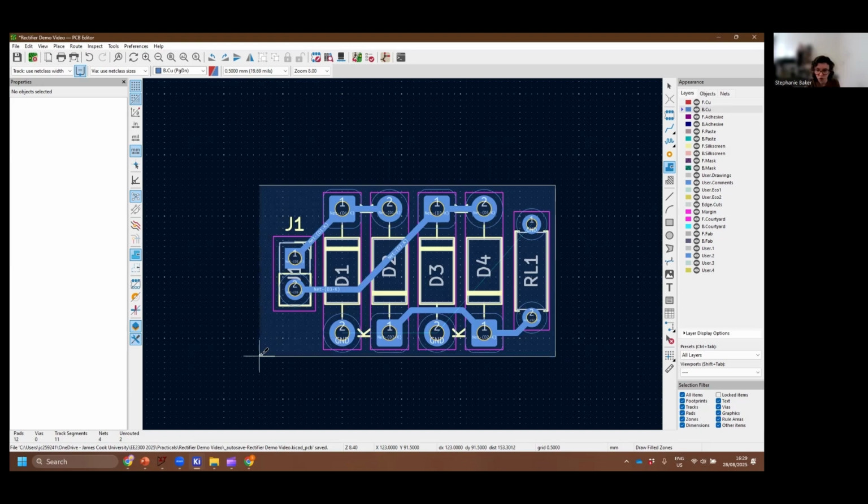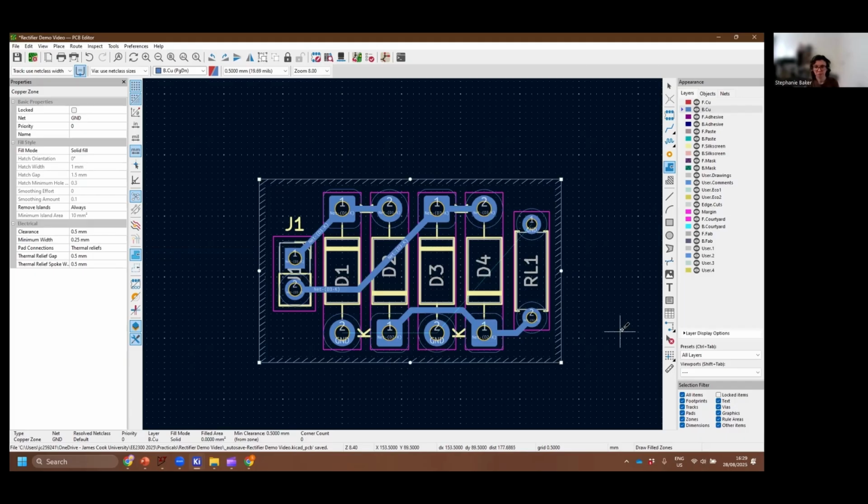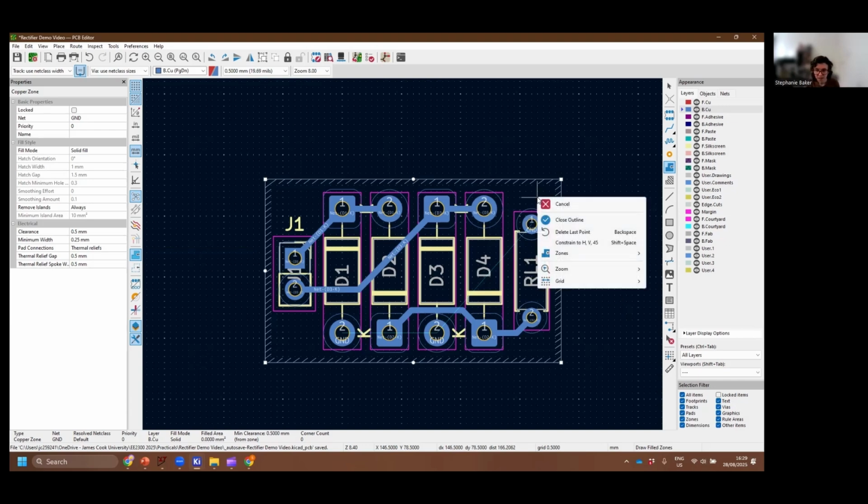And you don't need to leave a whole lot of clearance here. I might actually even bring this in a notch. I guess we could add slightly more clearance. Yeah, I'll add slightly more clearance just because it'll make it slightly easier to solder. It should still be pretty small. So there we go, we've got a little bit of clearance around each side. Probably can bring that one back in. So that's going to be our filled zone. And so then all of our ground will be connected to that.